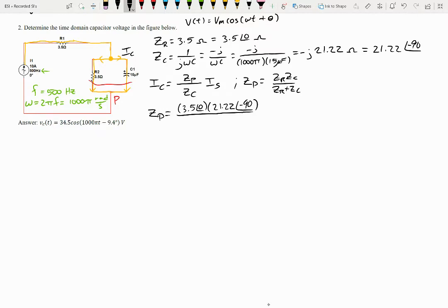All right, then now I'll plug in the other values in the bottom. These are going to be the rectangular values. Notice in the top how we have them in phasor, because if we're multiplying and dividing, we want to use phasor, and in the bottom, in the denominator, we're using rectangular. If we're adding or subtracting, remember we want to use rectangular. Okay, so when we multiply these out,